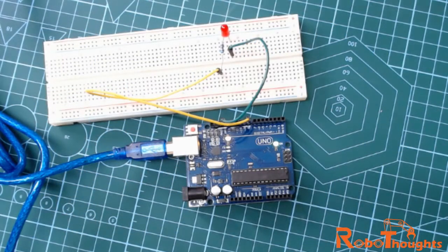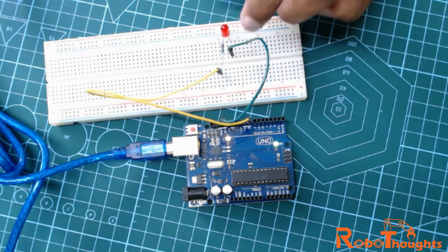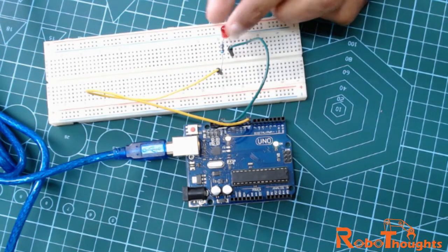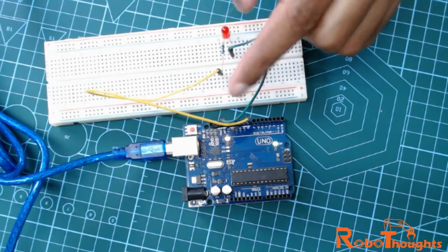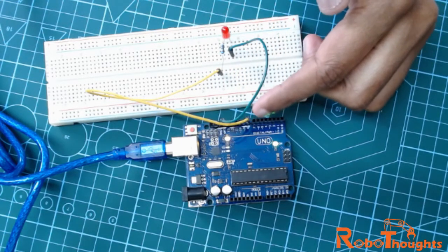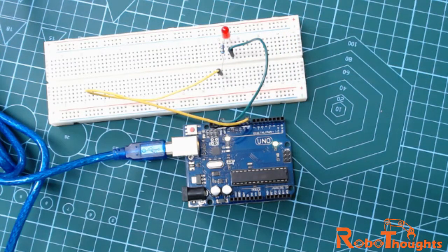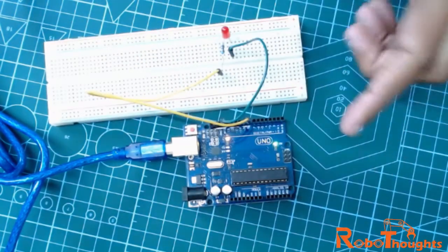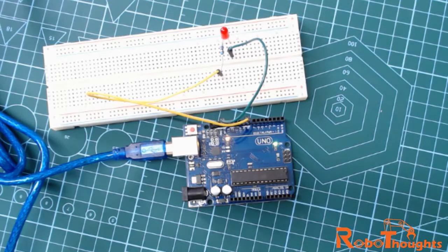So let me show you how I have connected it using a breadboard. And there you go, this is my Arduino, and this is the resistor which I mentioned above. This is the LED. Basically you can just pin up using the jumper wires and connect to pin number 8. You may use any of the digital pins, guys, it doesn't matter, but your C coding has to be according to that particular pin which you declare. So this is the very basic. I am going to show you how the digital write function works using this particular circuit.